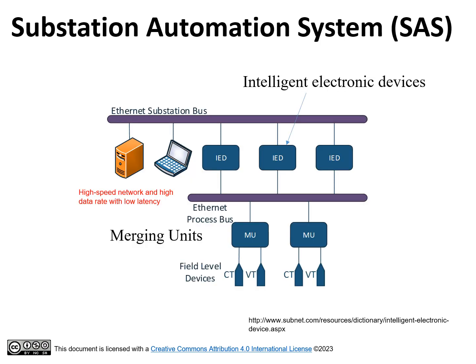Modern substation automation systems use an Ethernet-based network to interconnect substation automation equipment. Analog measurements are connected to merging units, MU, which convert signals from analog to digital and share them over an Ethernet network. Merging units are connected to an Ethernet network called the process bus and share all collected measurements with a high data rate. To ensure low latency and high throughput, merging units usually use layer 2 to communicate.